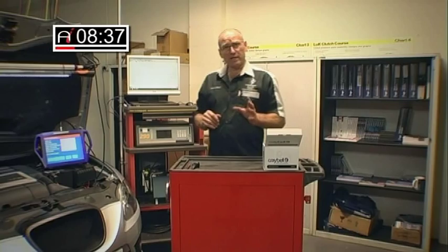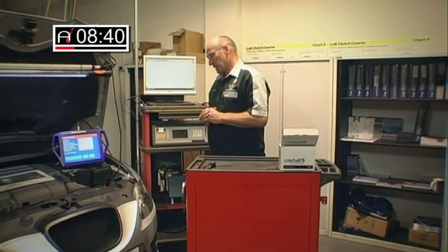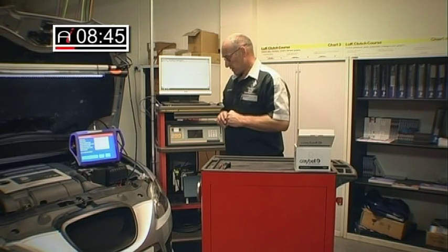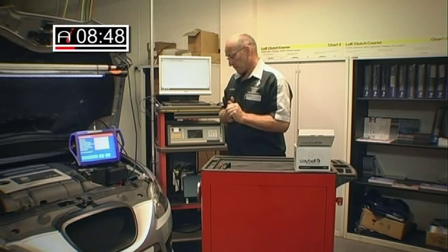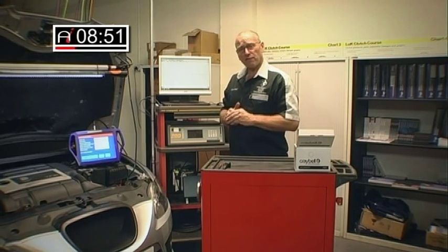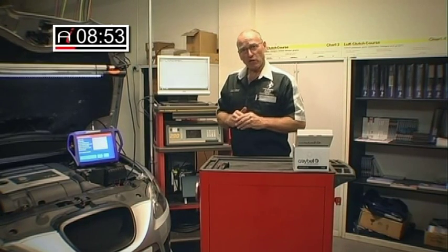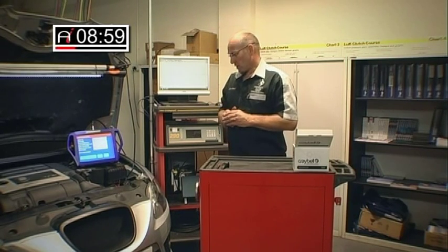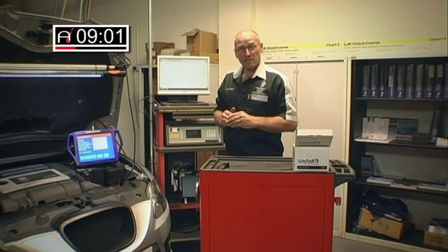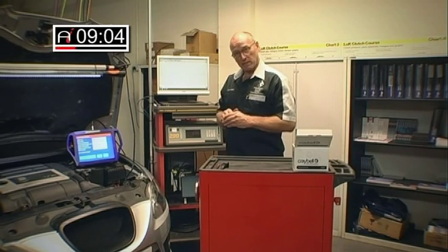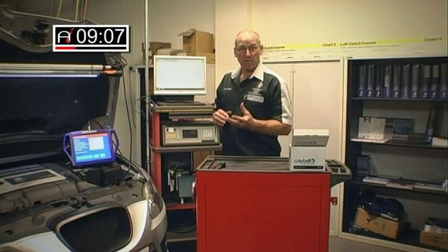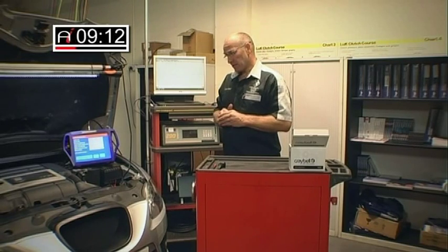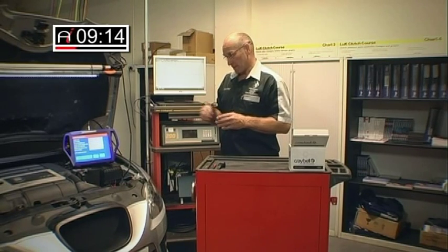What we've done just prior to setting up for the filming is I'd like to take a look at serial diagnostic opportunity first. I've often argued that serial diagnostics often shows symptoms, not cause. That doesn't mean to say I don't trust the process, I do. However, what I do is question the results of that process. And what we've done with this, I've set up some custom dynamics. In other words, I've chosen or cherry-picked certain key data from which I can evaluate this particular air mass meter. This is a digital air mass meter.